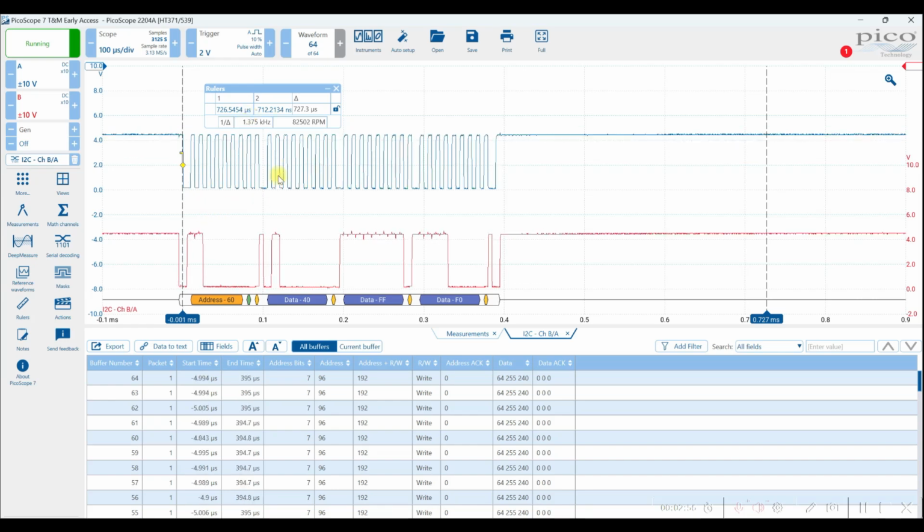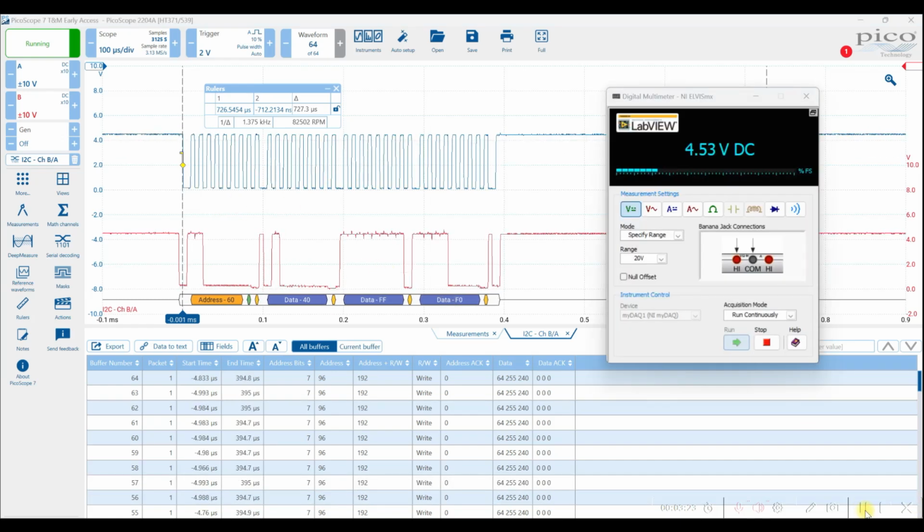Okay, the next thing I want to look at is whether everything seems to make sense. The first thing is that you'll see there are 4 groups of clock pulses. This is for the first byte, second, third, fourth, right here. The address we specified was 60, and these are hexadecimal values. Then the update-the-DAC command was 40, and we're sending out FFF. Remember that the last 0 is disregarded. Now that we have that information, everything seems to be okay.